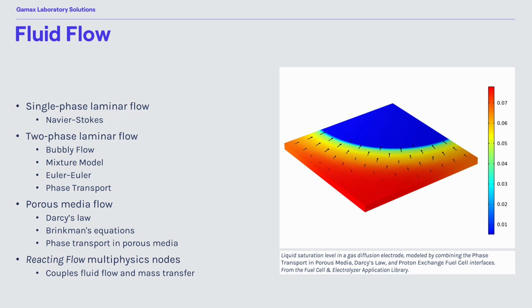Oops, too much fluid flow. Yeah, so it's possible to include the phase flow interface here. Typically, these are laminar flow interfaces, so that's the default that's enabled there. In most of the cases, that's suitable and enough. And it's prepared to do more than one, so it's prepared to do two phase flows with different predefined physics interfaces.